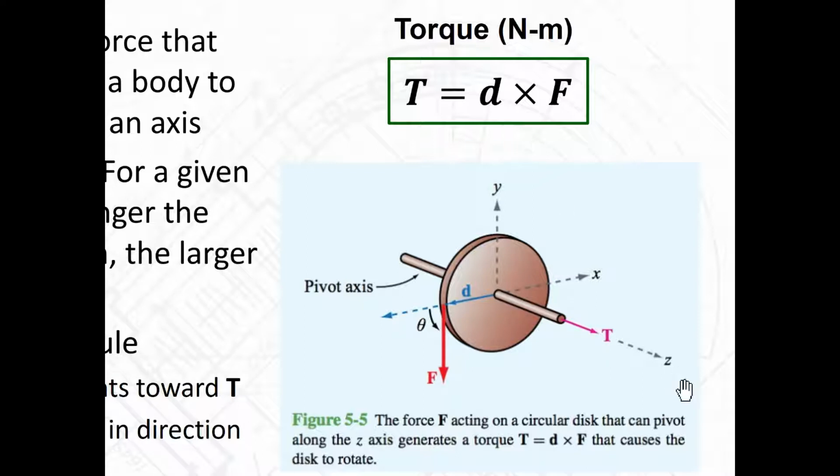It can go the other way too. If you have an electric motor that's known to apply certain torque, and you have a certain diameter or radius of wheel, you can calculate the resulting orthogonal force here. Let's look at the directions here. Directions are very important. D is pointed from the interior of the axis of the wheel to the outside of the wheel. T is pointed in the direction of the axis of rotation, and then F is perpendicular to both of them. So F, you can see here, is the force here. It's orthogonal to D. All right, so that's the force that would be on the end of that wheel that's generated.